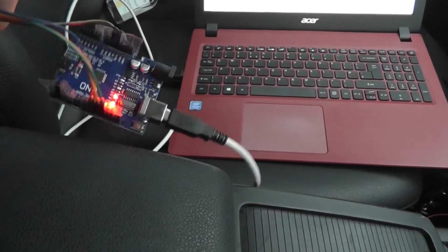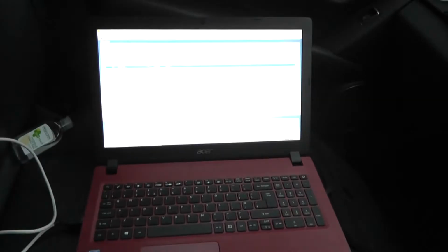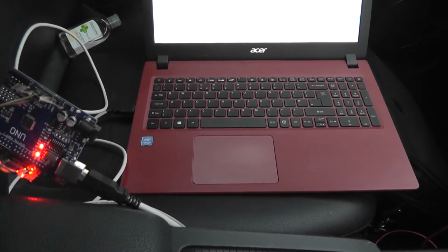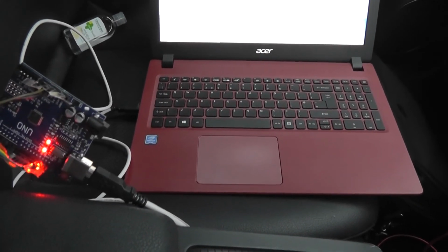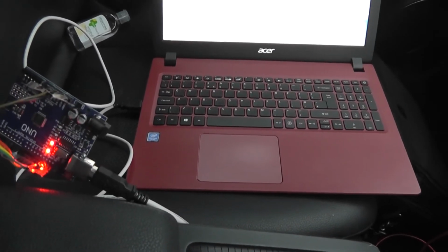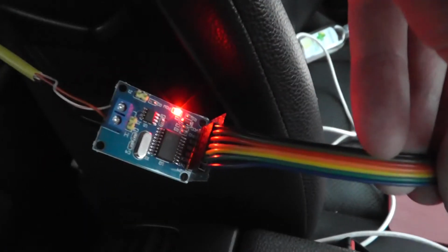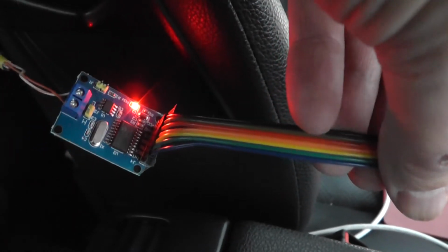Okay, well, just for completeness, I have already shown you that this software wasn't working with the Arduino Uno and the CAN bus shield. I suspect that's down to settings not being correct for it, because as you can see we're getting CAN, and that's coming straight from this Arduino, and I have patched it into the MCP2515 CAN adapter.